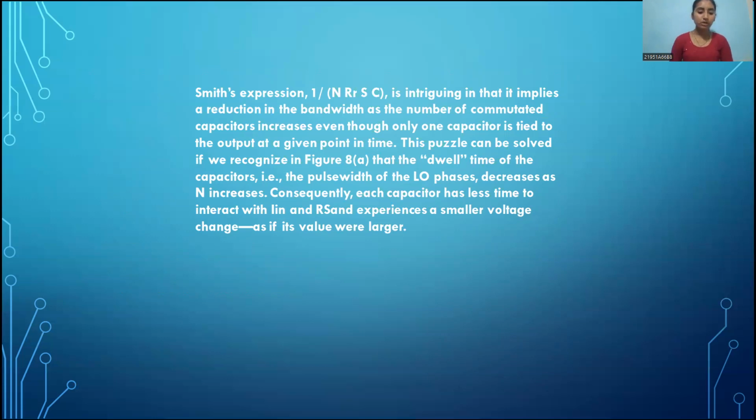This puzzle can be solved if we recognize in Figure 8a that the dwell time of the capacitor, the pulse width of the LO phase, decreases as M increases. Consequently, each capacitor has less time to interact with the input and must experience a smaller voltage change as its value is larger.